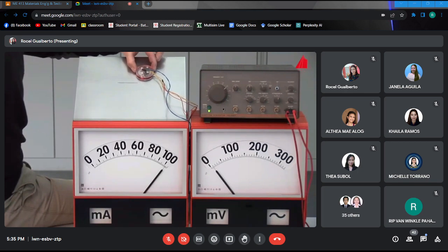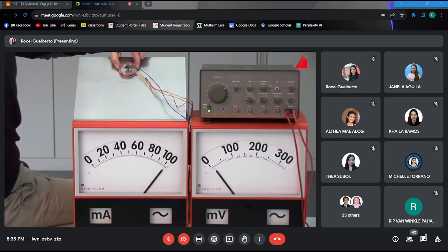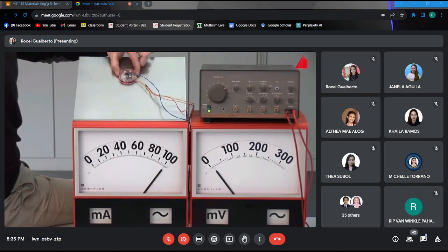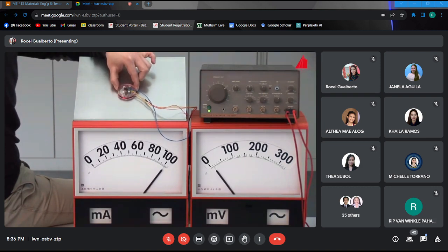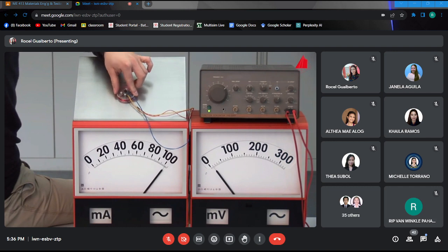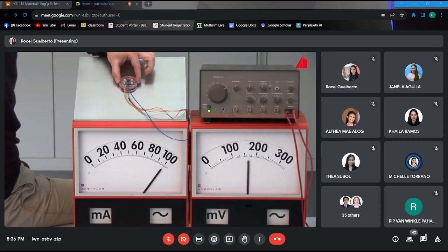The two D-shaped receiver coils must have the correct orientation for saw cuts and cracks. Otherwise you measure only little or nothing at all. If the orientation of cracks is not known, the probe is rotated by 90 degrees after the first pass and the test piece is scanned a second time.